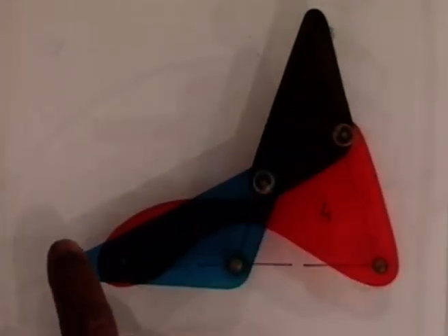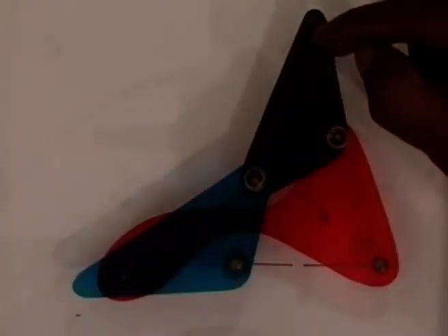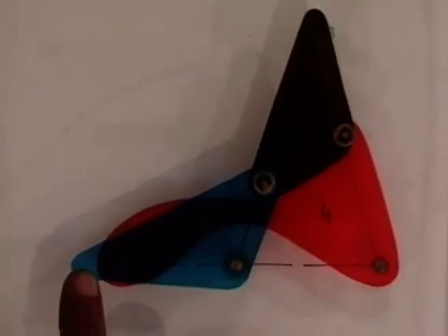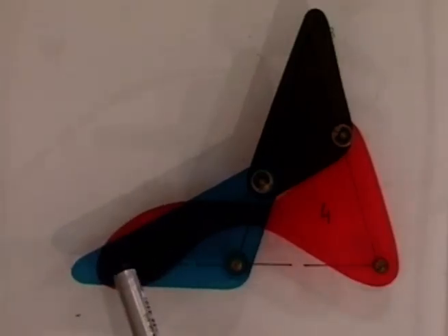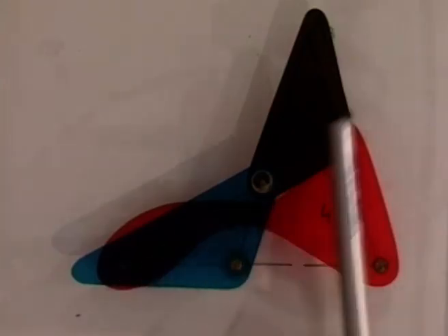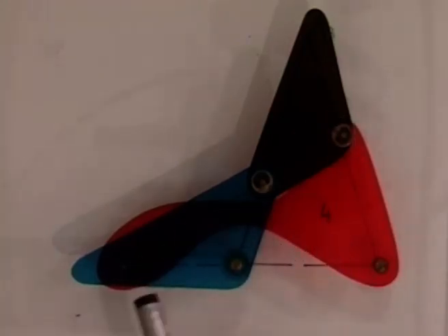You see, all other points in link 3 are moving around this configuration. This point has 0 velocity, it is hardly moving. Now, to see the significance of P24, let me consider a coincident point on link 2 and link 4. That means one point on link 2 and exactly just below it a point on link 4. These 2 points on link 2 and link 4 at this instant have the same velocity. That is why we call it P24.